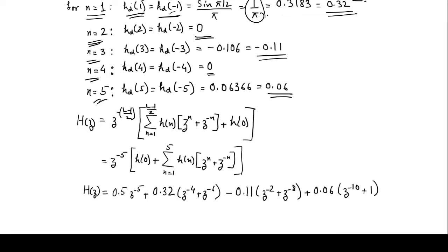That means what is happening? We are taking the past values, but filters should be designed with n values greater than or equal to 0. However, we have done that for the sake of easy calculation of the parameters. Otherwise, you would have to calculate all these h(n) values from 0 to say 11, right? 0 to 11 h(n).